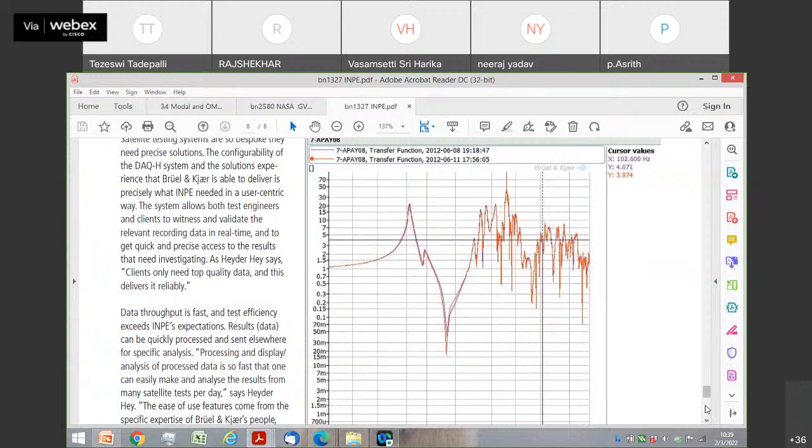So like the progressive wave tube, if we want like more dB, 170 dB, so we need some different facilities, because we don't have those type of tubes. We have only the standard impedance tubes, which is, as I said, used in both NSTL and VSSC. So there is a limit, like 160 dB, 158 dB. This is not done at high pressure. In such cases, for example, NAL does in the facilities is put the material in actual conditions in the reverberation chamber at 150 dB, excite it as a panel, and look at the absorption and transmission loss on an entire panel.